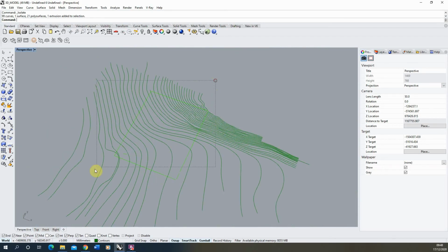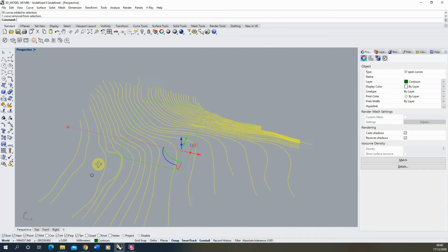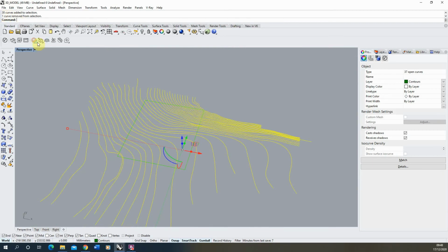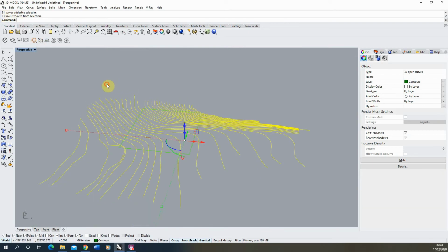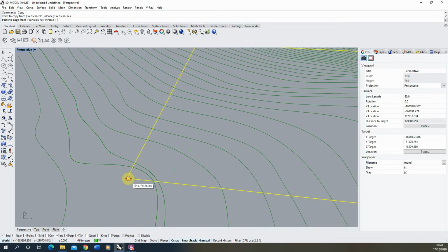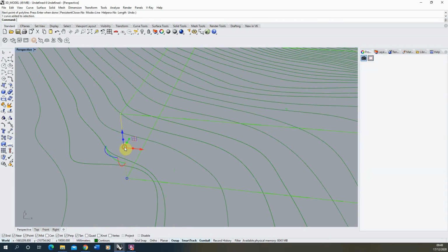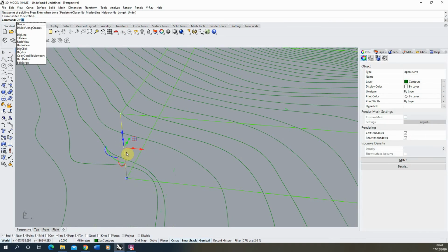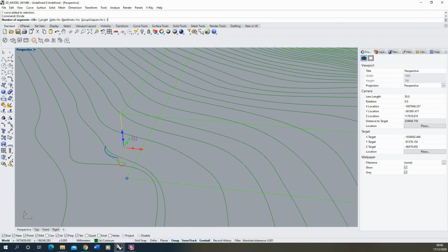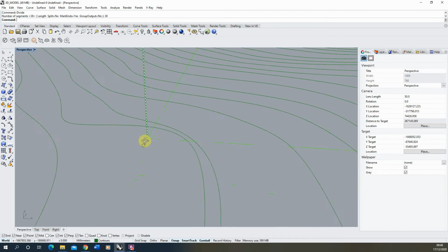The way I like to do this is I first select all my contour lines, and if I look down I can see in my selection here I've got 38 curves, so that tells me there are 38 lines there. Then I'm just going to copy up my site panel by 38 meters up there, and then I'm going to draw a vertical line connecting these points, and divide that line using the divide command by 38. That will then give me 38 1 meter segments on this line.